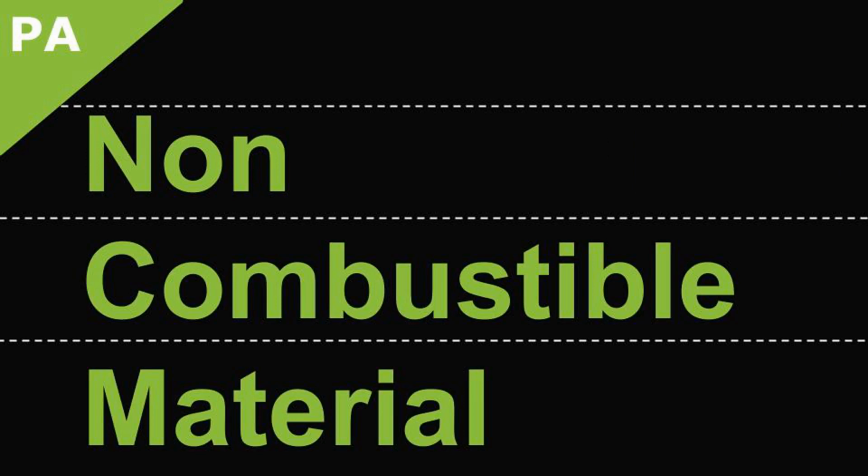Non-combustible material. Non-combustible material will not ignite or burn during a fire. The IBC qualifies a material as non-combustible if it is tested in accordance with ASTM E136, the non-combustible material tests, or if it has a structural base of non-combustible material with a surface not more than 1/8 of an inch thick that has a flame spread index no greater than 50. These requirements are located in Chapter 7, Fire and Smoke Protection Features.